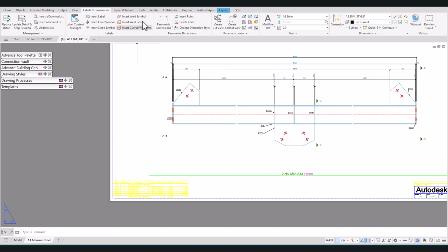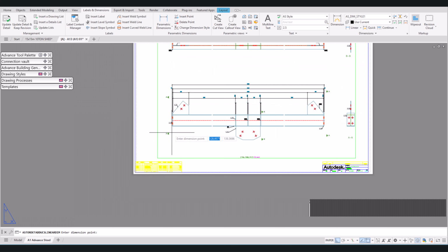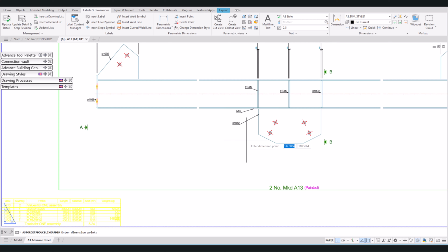So from there, let's detail the bottom gusset. Mind you, you don't need to give too much information, but you need to give enough information for the boilermaker to assemble this thing, right? Since this is an assembly, you're going to have drawings for the parts, so you don't want to give too much information. Also, if you give too much information, it's going to take a lot of your time on your detail.